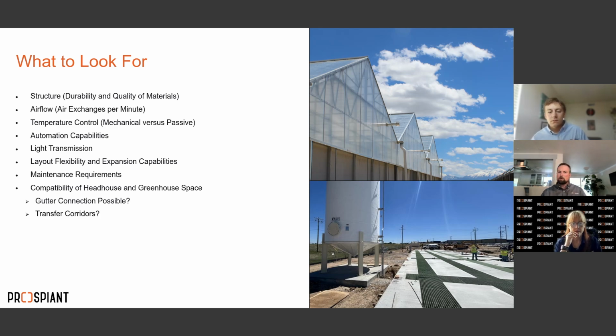So we used to build a lot of our fish buildings out of metal. So we still had the metal framework, but we used to cover them in insulated metal roofs and walls, and they've held up very well. But more recently, we've been finding that they make non-transparent polycarbonate materials that you could put on a roof, and you still get a reasonable R value. Remember, in the fish house, you're really more focused on the water temperatures, not as much on the air temperatures inside there. You still get a reasonable amount of insulation, but you lower the cost to construct the fish house.